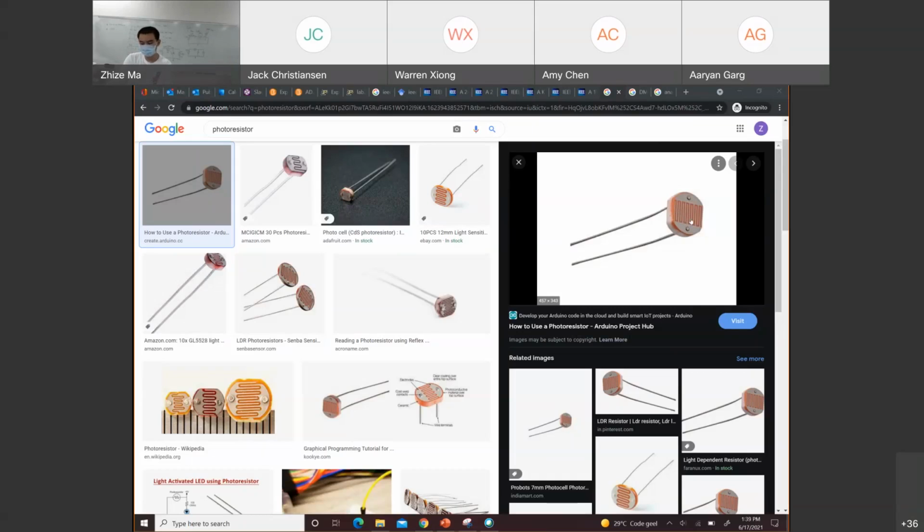If you can't do that, you can find something to cover the circuit so this can work better. So what you will do is let this component face different bulbs. For example, you let this photoresistor face this bulb first, use your DMM to measure the resistance, and record the data.